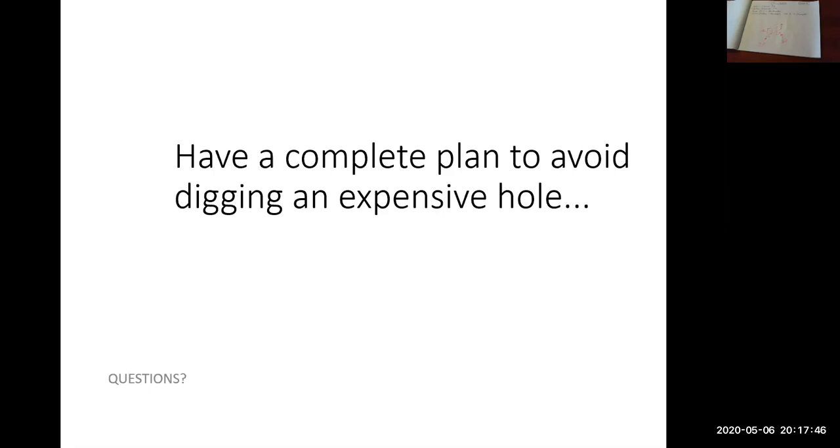Maybe it's not a building, maybe it's a water pipe that's in the ground 2 meters away. Is there physically room to make that one-to-one cut slope and not undermine or expose that water line? Exposing the top of a pipe is fine. Digging underneath of an existing pipe is a no-no. You shouldn't do that unless you've supported it in some fashion. So again, using your pen and pencil on your drawings to draw things to scale is highly recommended.